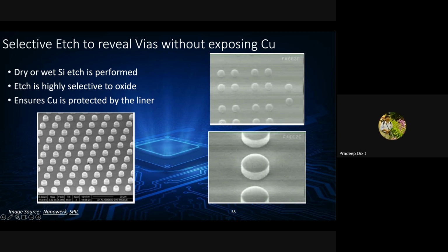One more thing, if I may ask. You said something about wet chemical etching, right? Is it going to be something like EDP etching or something else? Well, the studies that I have seen, people use things like TMAH, for example. But TMAH will give you anisotropic etching; it is going to be crystal plane dependent etching behavior. But here, when you are doing this kind of wet chemical etching, you want to make sure that it is isotropic. That's why I was curious about the wet silicon etching.